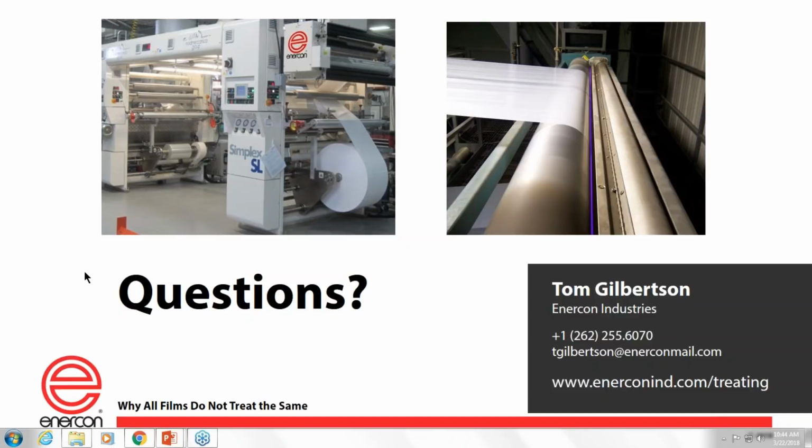Uniformity in corona treaters is typically a result of the geometry between the electrode and the film. So if the electrode gap between the film and the ground roll is uniform, meaning that up and down it's uniform, in the web direction it's uniform, the end result, meaning the dyne number in this case, should be uniform.